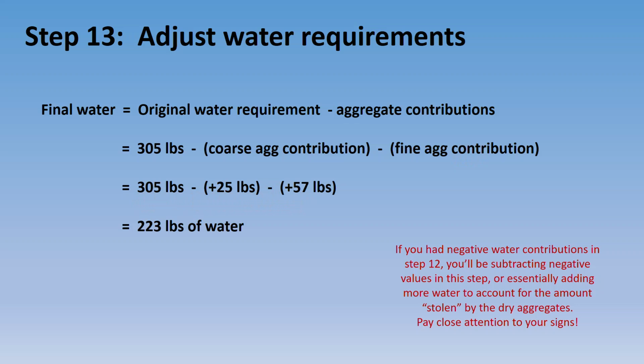So the adjusted water requirement is now 223 pounds of water that we need to add because our rocks are bringing in a lot more for the party. Total, they'll give us 305.